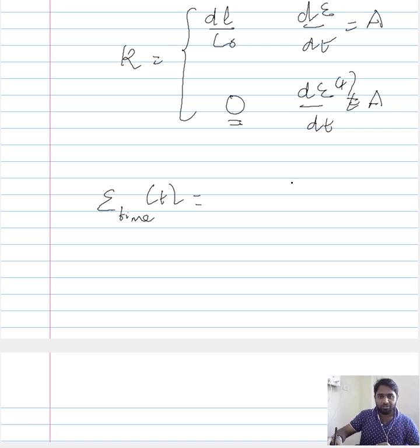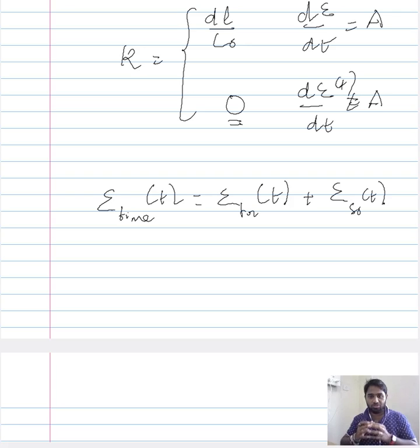So these two different terms involved: the one that related to the transient creep, and the other that related to the steady state creep. So there were two different terms that were used by Andrade in the expression that considered the overall creep curve. In addition to the time independent zone, the time development zone comprises two terms. One term relates to the transient region, the other relates to the steady state region.